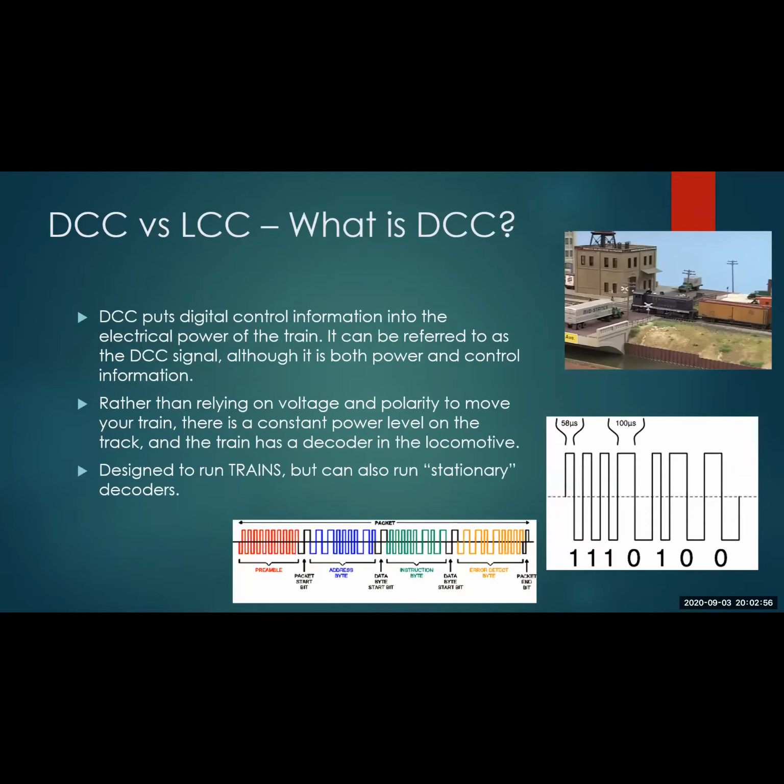So what is LCC and what is DCC? Let's talk about that for a minute. DCC, digital command control, puts a digital control signal onto the track itself. And it's not really AC. In the diagram at the bottom, you see red, blue, green, yellow. It's like AC, it alternates back and forth, positive and negative, but the width of the pulses actually communicates data, zeros and ones, in the lower right hand. So it communicates as well as powers. I think most of you know that, you have an intuitive understanding of that.